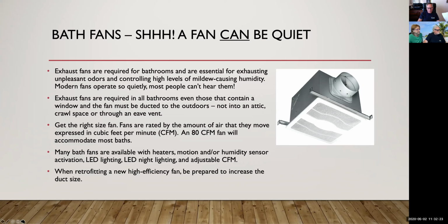A medium density fiberboard or MDF can be veneered on one or both sides with wood, melamine, or plastic, just like plywood. However, it's much heavier and not nearly as strong as plywood, and it doesn't hold together as well as plywood. Wood veneer interiors can also be painted or stained with MDF, but it's less expensive than plywood. So you get what you pay for. If you want a strong cabinet, you look at a plywood case with a dimensional lumber frame in the front. If you want a more inexpensive cabinet, you look at MDF.